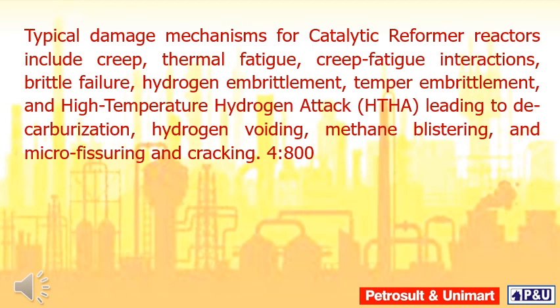Typical damage mechanisms for catalytic reformer reactors include creep, thermal fatigue, creep-fatigue interactions, brittle failure, hydrogen embrittlement, temper embrittlement, and high-temperature hydrogen attack, HTHA, leading to decarburization, hydrogen voiding, methane blistering, and micro-fissuring and cracking.